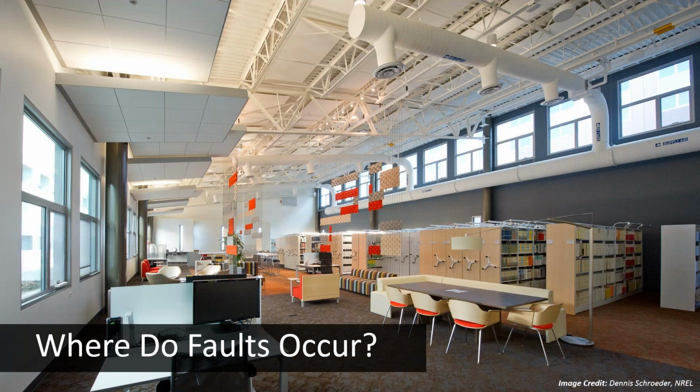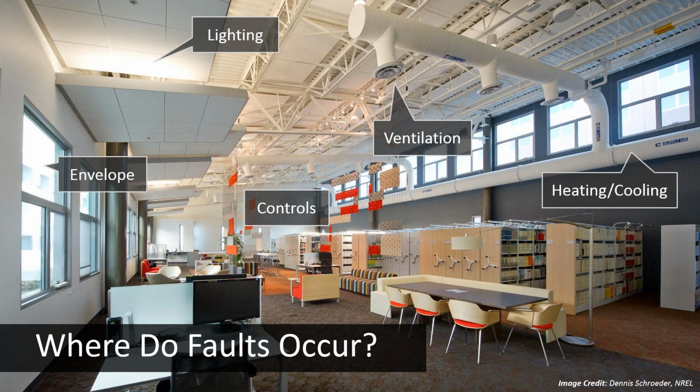And the ones that are mainly addressed in AFDD algorithms, fault detection and diagnosis algorithms, are the heating and cooling system, which is often combined with the ventilation system, providing fresh air to the occupants of the building, the lighting system, what I just called the envelope, which is basically the walls, windows, doors, roof, or the control system of the building.